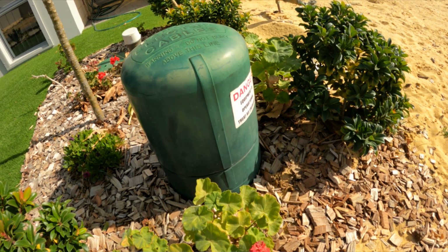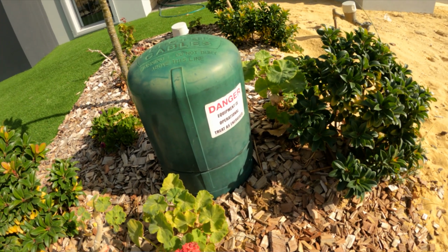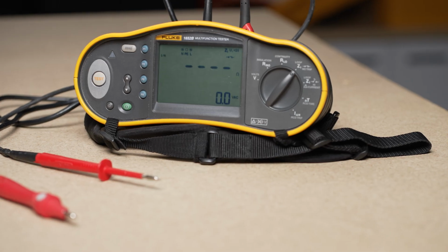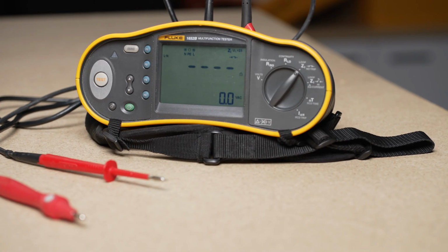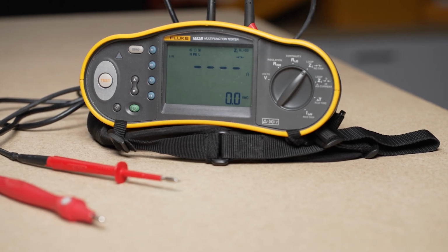The network-operated distribution cables are larger than individual installation cables and therefore have much lower impedance. However, as the external part of the fault loop, they will still contribute to the overall fault loop impedance values. This is why a fault loop impedance verification test is recommended to be conducted using a suitable meter once power is available.